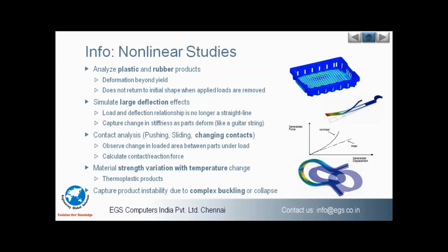So this study you can do with the nonlinear analysis, and we can study the loads and the deflections using a straight line, say when our product is no longer going to exhibit a linear kind of behavior. And we have the contact nonlinearities also when we are dealing with the pushing or sliding movement on the contacts. We are going to observe the change in the loaded condition for the parts when the load is being applied. So we can also calculate the contact reaction or the reaction forces.